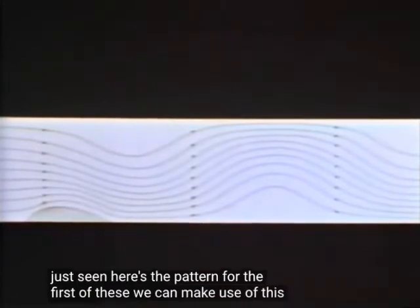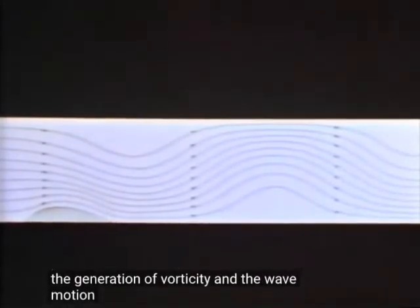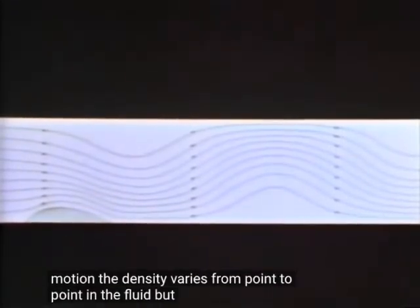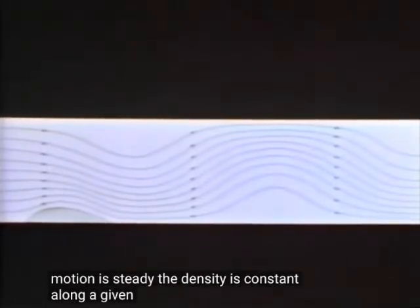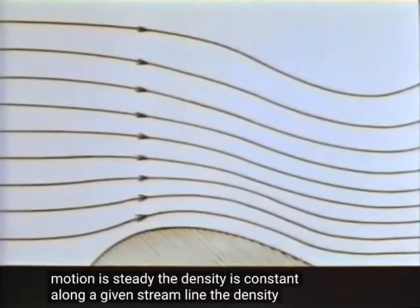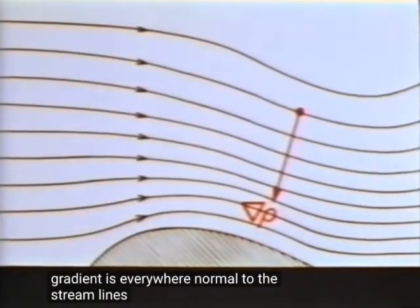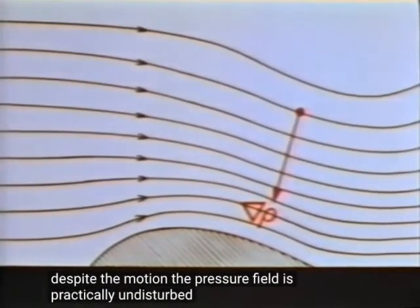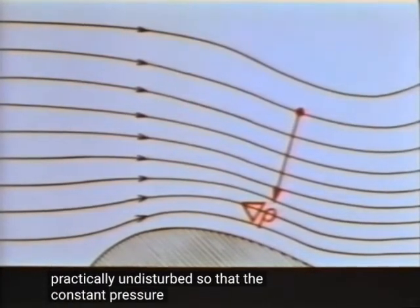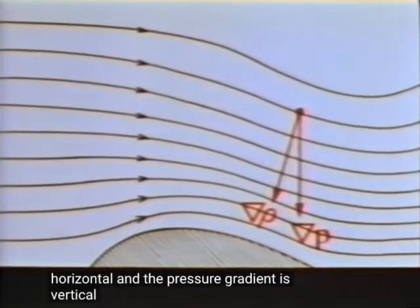We can make use of this pattern to show the relationship between the generation of vorticity and the wave motion. The density varies from point to point in the fluid, but because the motion is steady, the density is constant along a given streamline. The density gradient is everywhere normal to the streamlines. Despite the motion, the pressure field is practically undisturbed, so that the constant pressure surfaces are nearly horizontal, and the pressure gradient is vertical.